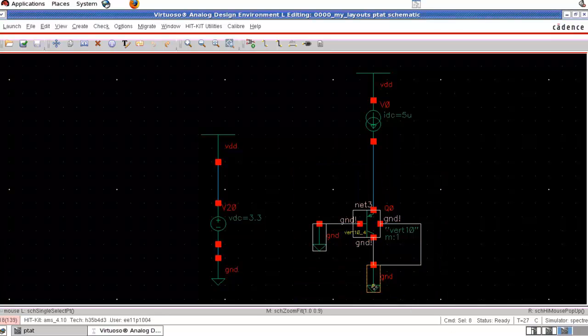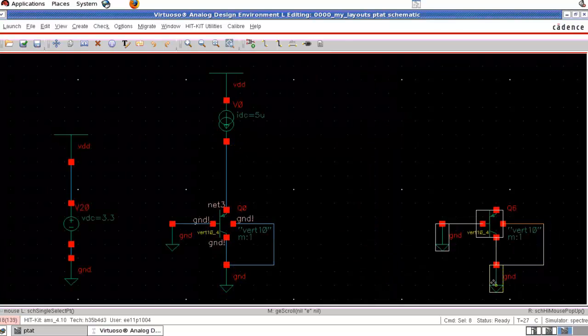So when we were doing the theory, we said the number of diodes we connected was n. We connected n number of diodes in parallel. So in the simulation I am using n equal to 2. That is, we are connecting 2 diodes in parallel. So I copied that and I'm copying this diode.